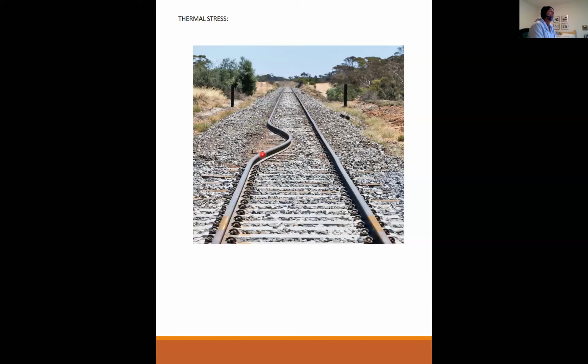I don't know how much expansion that actually represents, how much it swayed to the side buckling. This thing may have only wanted to expand 1/4, 3/8 of an inch. And this splice right here and right here didn't allow it to expand by 3/8 of an inch. So that's what you get if you don't let it do what it wants to do.